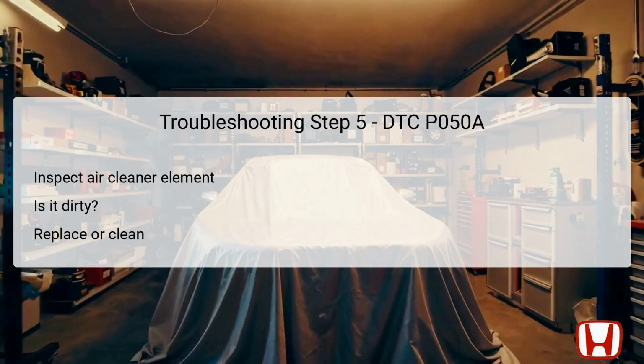This step focuses on inspecting the air cleaner element for dirt or debris. A dirty air cleaner element can severely restrict airflow, impacting engine performance, especially during cold starts. It is vital to determine if the element is indeed dirty. If so, the necessary action is to either replace it or clean it thoroughly. Doing this will help restore proper airflow, which is critical for accurate air-fuel mixture regulation. Maintaining a clean air cleaner element is essential for optimal engine operation.